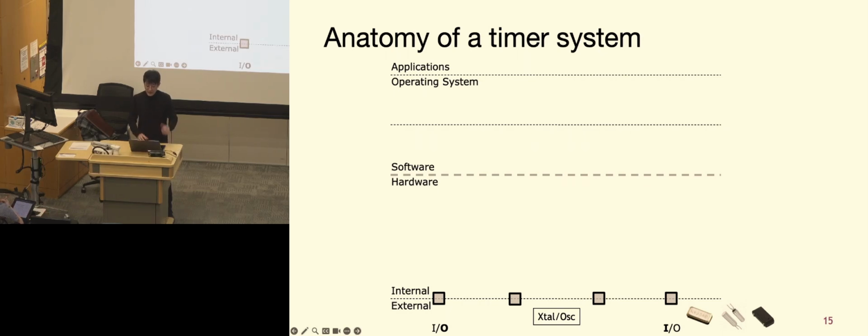You usually have some kind of clock source internally for additional timers if you don't want to use the external crystals, but they're not as accurate. The external crystal is still, I think, the go-to solution for most events at a lower frequency.